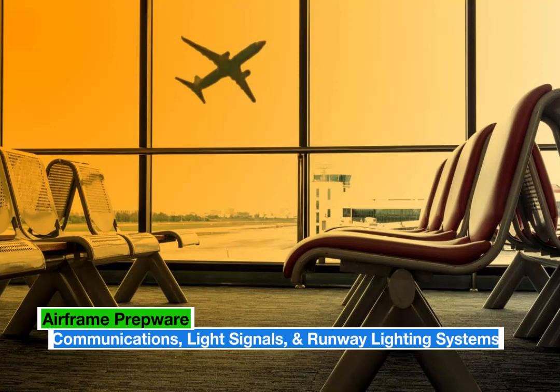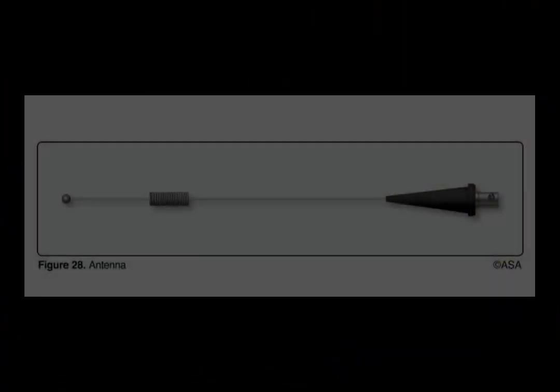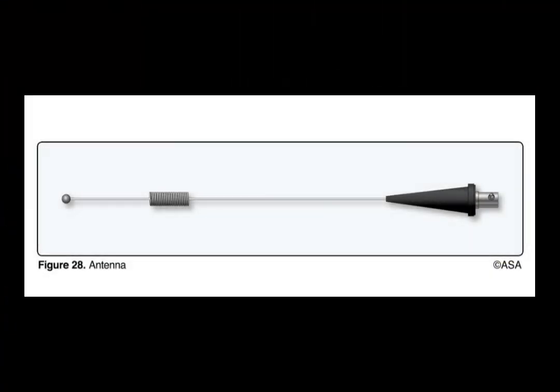Installed radio equipment is protected from damage due to jolts and vibrations by shock mounts. When installing a DME antenna, it should be aligned with the centerline of the airplane. Refer to Figure 28. What kind of antenna is this? An ELT antenna.